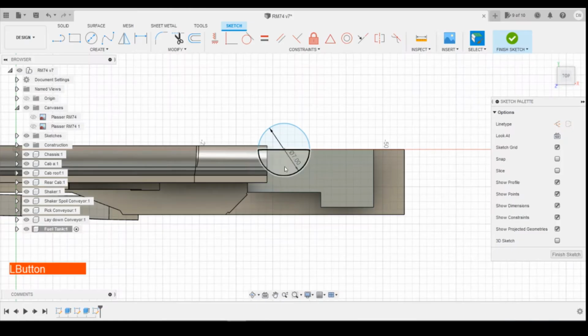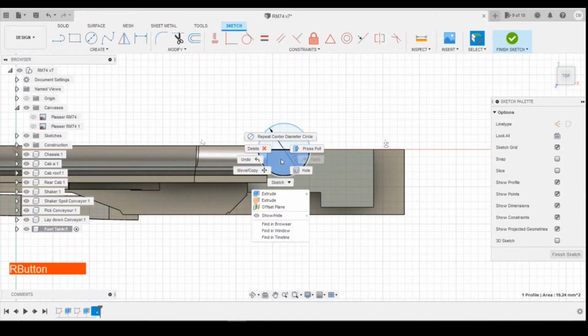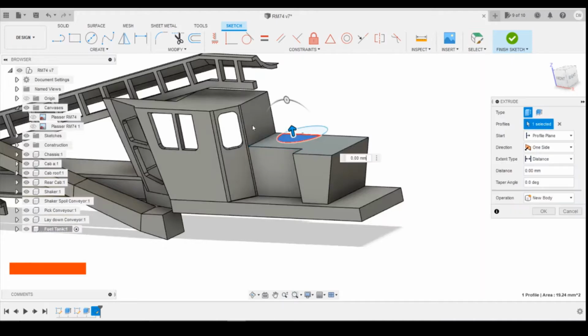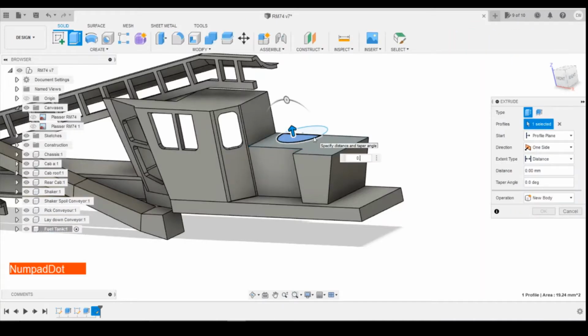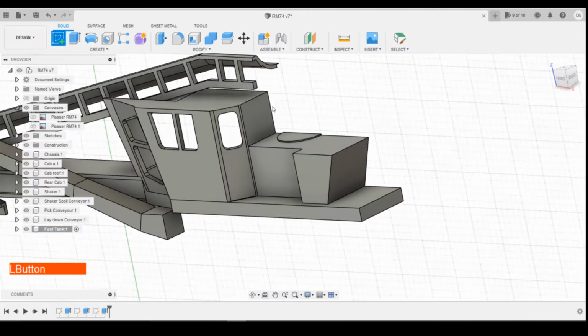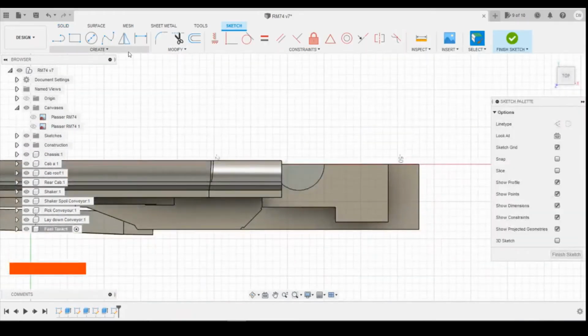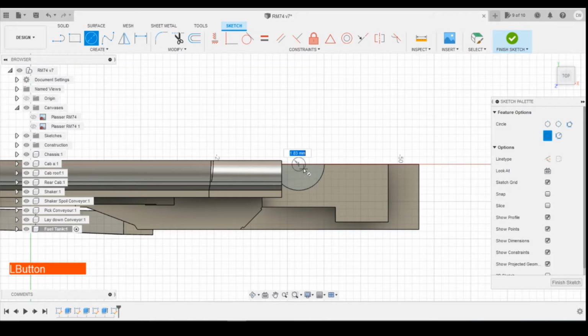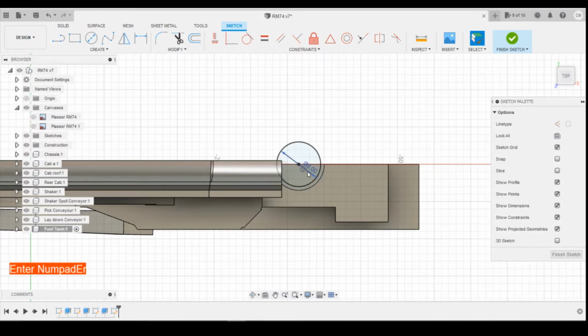Yeah, no, that's probably not far wrong from where we want. And I'm only going to use half of the circle drawing. I'm going to bring that up by 0.15, and then I'm going to draw on that top surface another circle using the midpoint. And we're going to come slightly under 7 millimeters. So I'm going to say 6.5, no, 6. I want it to step in a little bit.